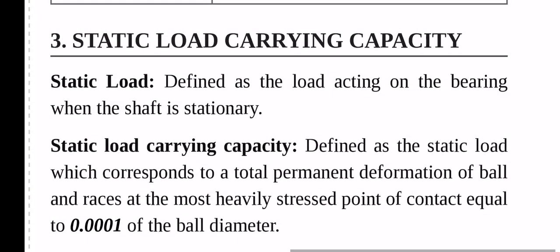Static load carrying capacity. Static load is defined as the load acting on the bearing when the shaft is stationary. Static load carrying capacity is defined as the static load which corresponds to a total permanent deformation of ball and races at the most heavily stressed point of contact equal to 0.0001 of the ball diameter.